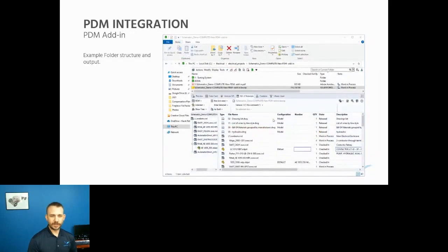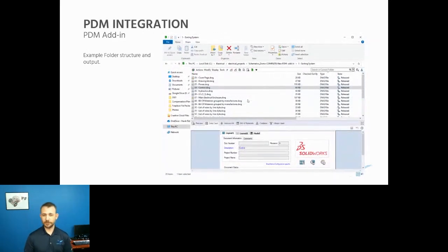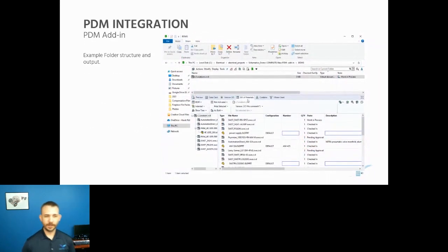Okay. So if I take a look at my actual TEW zip file, which is the archive, and I go to the BOM tab of the preview down here for the PDM integration, I get a bill of materials. So you get that full bill of materials there, you get where used, all that information pops up available there for you, right? Drawings, DWGs, they get exported also. So that information gets put in there and filled in for you. All right. And then under BOMs, there is the virtual document bill of material there also. So you can see that information is set there also.